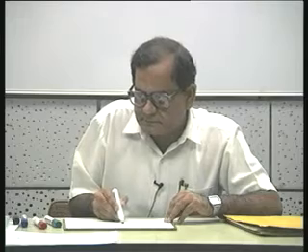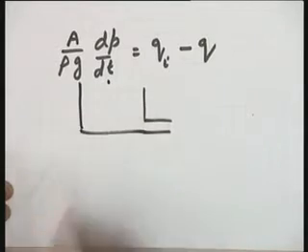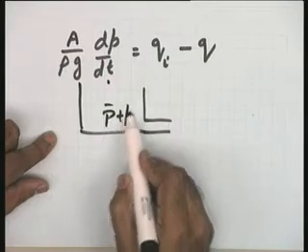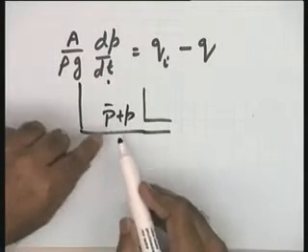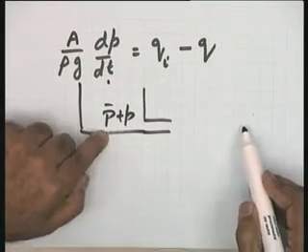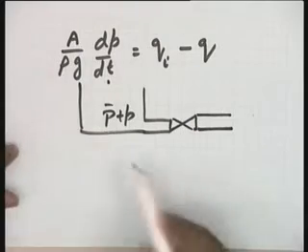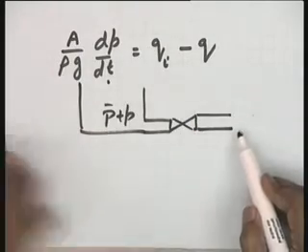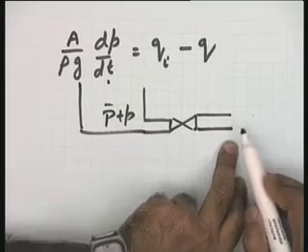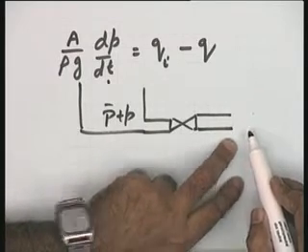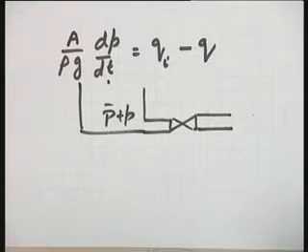Del P in this particular situation, this is your tank. Del P in this particular, this is P bar plus P, will be affected by this pressure and the atmospheric pressure. Please see the pressure across this orifice. On this side there is no tank here. It is the atmospheric pressure as far as the present situation is concerned. So, what is the atmospheric pressure and how do I take the variables?